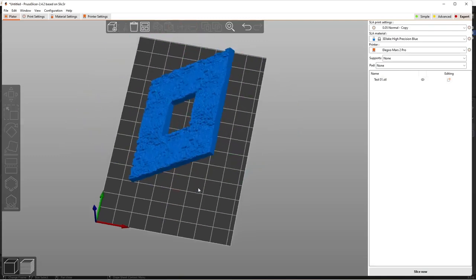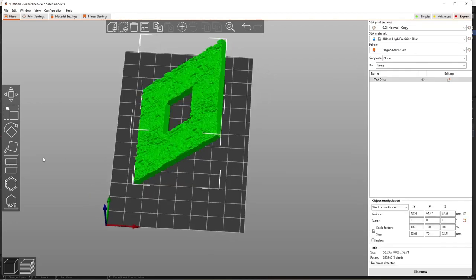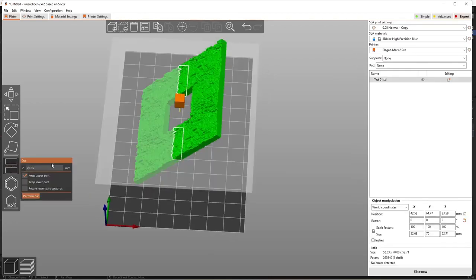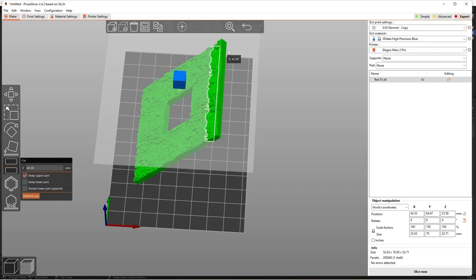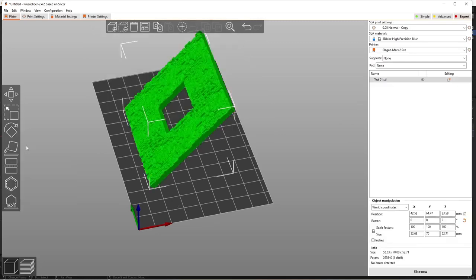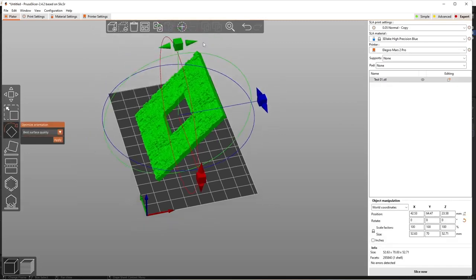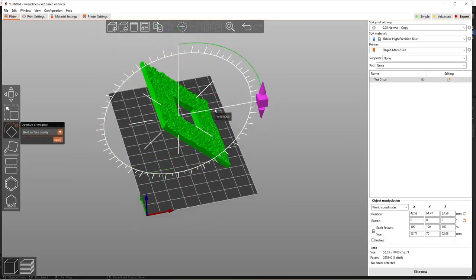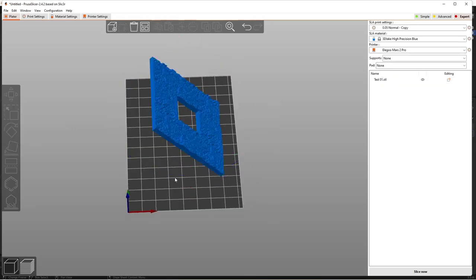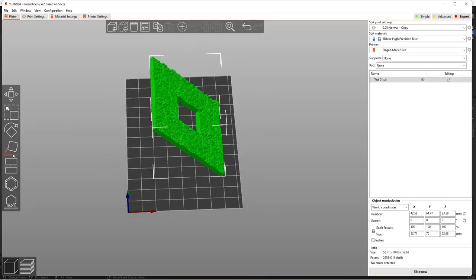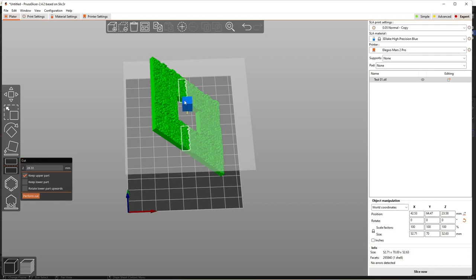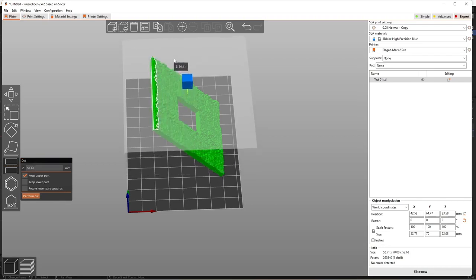It's a learning curve for me as well. There we go. Click on it, use our cut tool, bring it up. No, I was right in the first place. Rotate, back again. Sometimes I do wonder. Right, now we use our cut tool and we chamfer this edge.